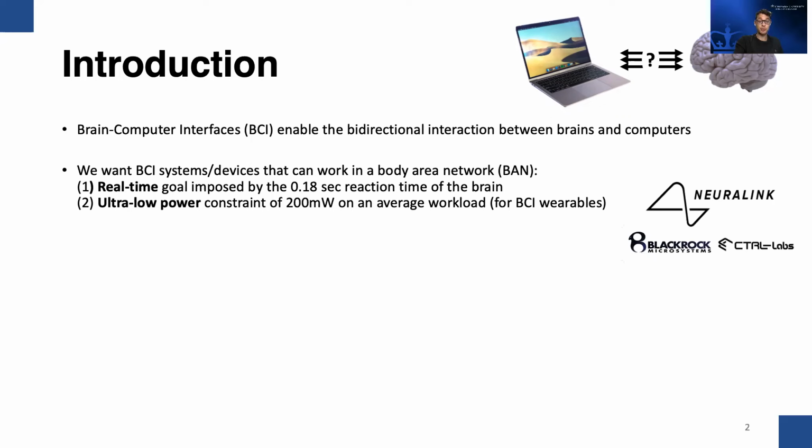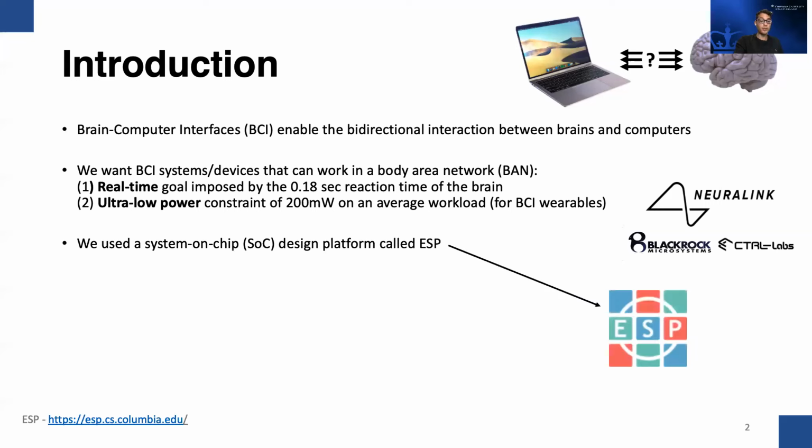Two, the system needs to meet ultra-low power constraints of 200 milliwatts in order to be located as close as possible to the human body as an edge device and the BCI wearable. In our work, we focused on hardware acceleration of the algorithms that analyze the brain data. We used an open source SoC design platform called ESP as the base structure of our SoC architecture.